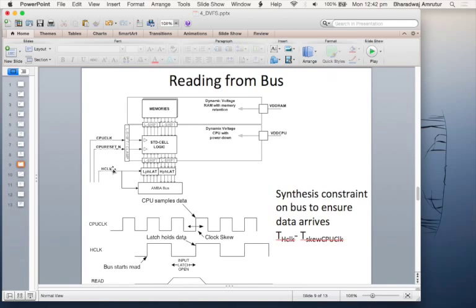Instead, what is done is the following, where you have your clock to the bus and the CPU clock, which are all synchronous. That means they are derived from the same PLL, except that the CPU clock might be some integer multiple of the bus clock. Either it's exactly the bus clock or a couple of times, 4 times, etc. Because typically CPUs will be faster than the bus. So they will be aligned, except that there could be clock skew out here. That means even though the frequencies are aligned, there could be some uncertainty in the delay relationship.